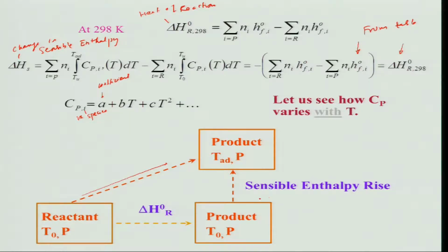Even if it is non-adiabatic, the temperature will still increase, but you will get a temperature lower than the adiabatic temperature, since some heat might be going out. In a real system there is no adiabatic temperature as such; it is just a theoretical one. Suppose I want to burn some fuel and oxidizer in a burner, can I get the adiabatic temperature? It is quite difficult, because some heat has to be transferred to the atmosphere. Even though you can insulate, some amount will still go out. You cannot make insulation 100%, right. As a result, Q, the heat transfer from the system, cannot really be 0, whatever you do.